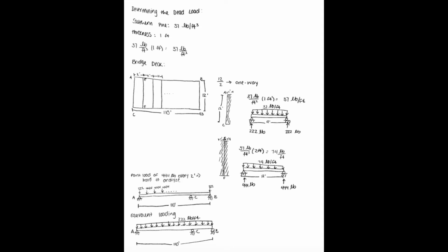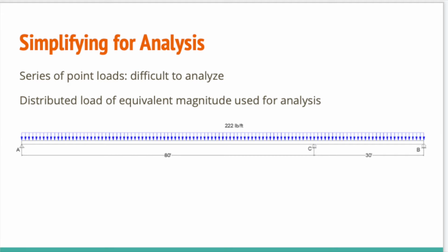Originally, we tried to calculate this as multiple point loads, but we found that for our analysis calculation later on, it was much easier to simplify these point loads into one distributed load.